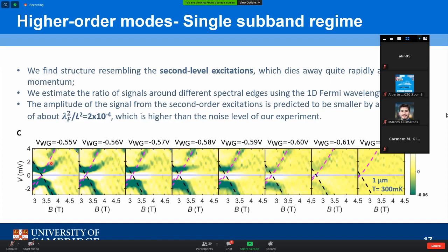As one last thing on this data, if you look carefully at negative bias, there's sort of a kink here. This wouldn't be cause for much, warranted only observed for 1 micron devices. And so, 2 replicas are clearly visible, but if you want to be optimistic, this could be evidence of a third replica as a shadow band to the second level replica. It seems to show some response to the Y-gate. Of course, in order to be sure, we would have to go to submicron lengths, which we haven't done yet. But of course, once you go submicron, at some point you need to ask yourself, when does it stop being a quantum wire and become a QPC?